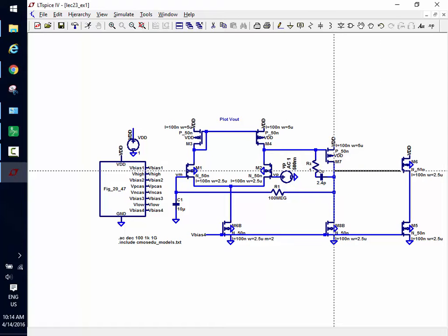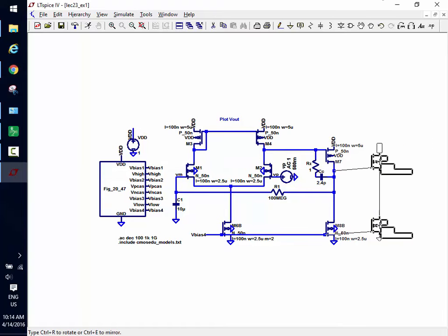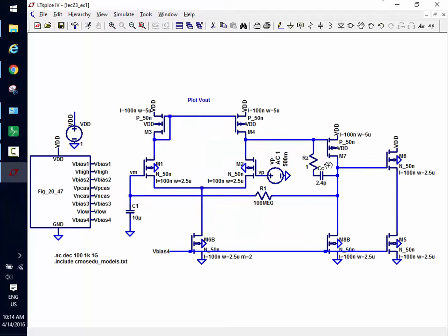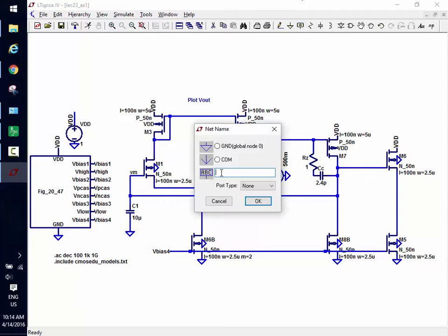And what's the purpose of the source follower? Tell me in simple language that shows you know what you're talking about. Yeah, so it doesn't load the output of the common source, so I can drive a resistive load without killing the gain. Because if I put a resistor here, the mega ohms that are there are going to be loaded, right? So then let's call this V out, and it's going to be an output.